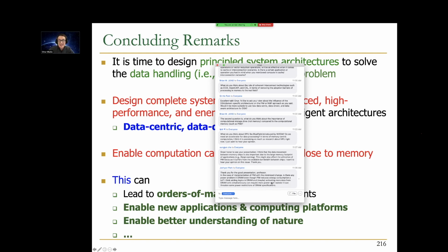So I think we need to change the mindset in terms of thinking about power consumption and also thermals of DRAM devices. We may need heat sinks for DRAM devices, of course, depending on where you employ them. But I think like the TFAW, for example, for activate windows, those kind of characteristics, I think we need to rethink some of those going into the future, because they will be limiting your performance if they're solely there to limit power. And I think that's a very good direction also. How do you actually design a DRAM chip to have good power and good reliability characteristics that can sustain in-DRAM computation? That's, I think, a great research topic as well.